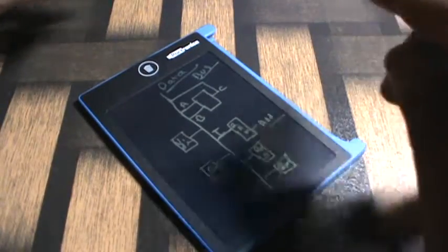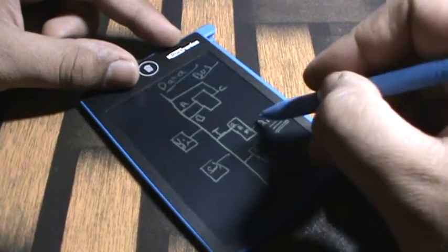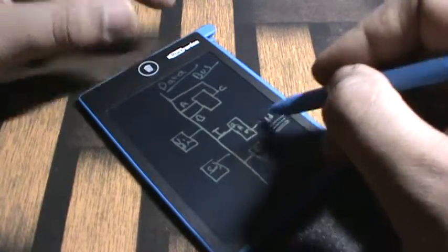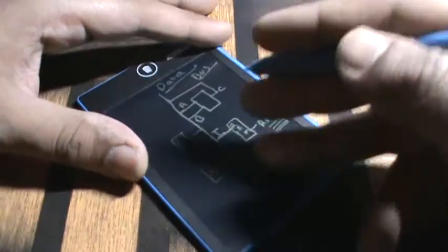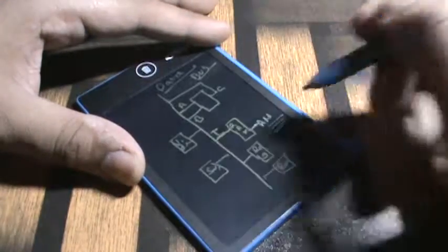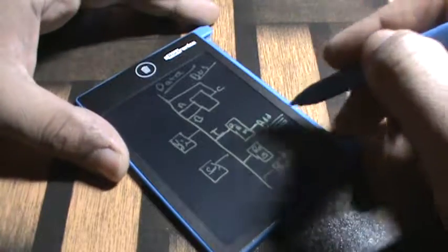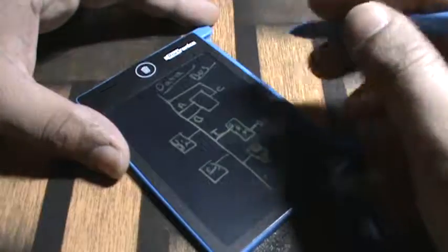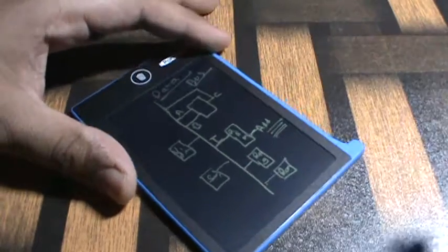There's one more bus which is known as the address bus, which is right here. I'm showing this pin as floating right now, but it's not floating. It's connected to another bus which will be parallel to the data bus, and the address part of the RAM, ROM, video chip or sound chip, whatever chips we have, will be connected to the address bus, but we will come to that point in a minute.